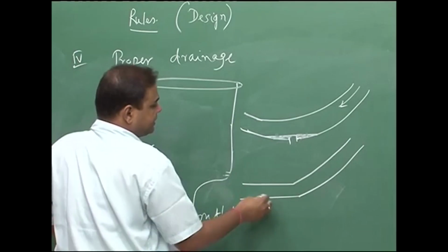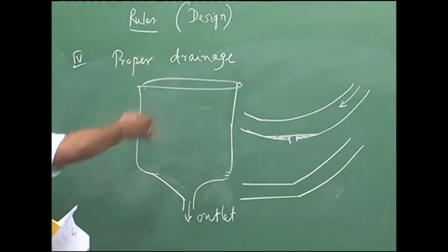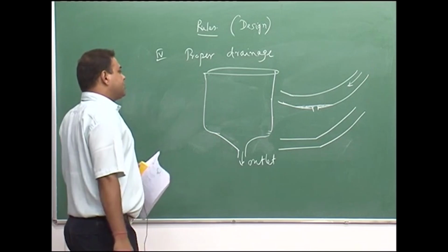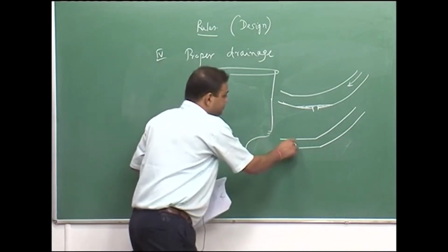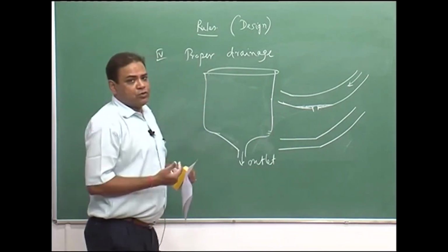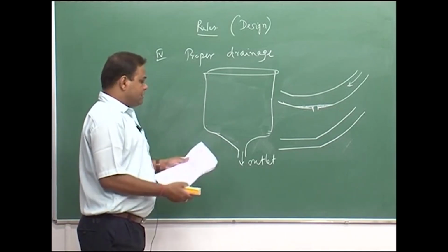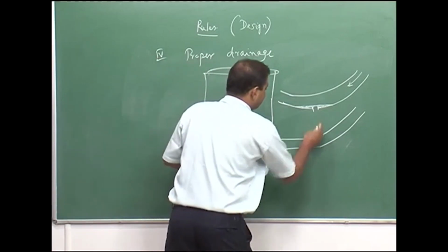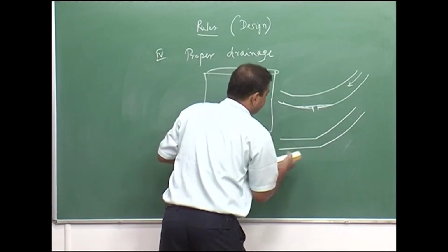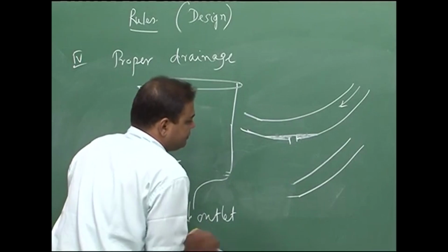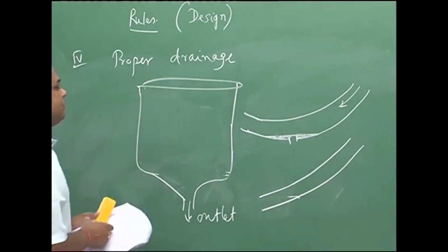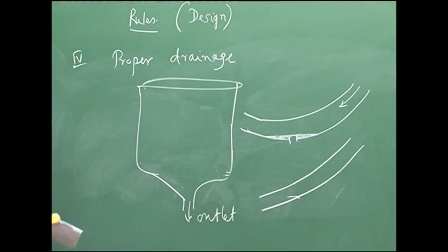There should be a constant angle, so that all the liquid can go out and cannot stay in the pipeline even if the plant is not working. Instead of this, we can have a design like this, always having a slope downwards, so the liquid can always flow out even if it is idle.